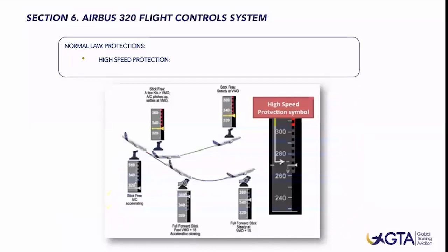So if we apply side stick lateral deflection up to 33 and we release the side stick, the airplane will keep turning with those 20, 25 or 30 degrees bank angle turn. But if we increase our lateral deflection over 33, say up to 45 degrees, and then we release the side stick, the bank angle will turn back to 33 degrees.